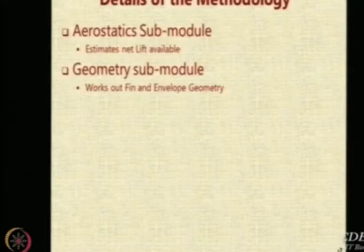Then there is a geometry submodule. This works out the sizing of the fin and the envelope. So I must say that this methodology is only for conventional airships. Airships which will have a single envelope, axisymmetric body of revolution, and they will have a fin. They will have in fact four members, 2 vertical and 2 horizontal, which will be the fins. So we have to figure out some way of sizing the fin. Given an envelope, what would be the appropriate fin?